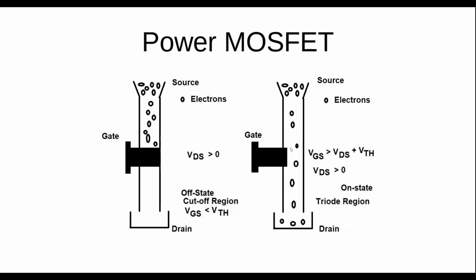Because you're going to have heat, you need a heat sink, maybe a piece of aluminum with fins, and in addition to the heat sink, you may have a fan running, just to make sure that it keeps cool, because if it overheats, then it will fail. So we want to find a way of cooling it so that it doesn't fail.